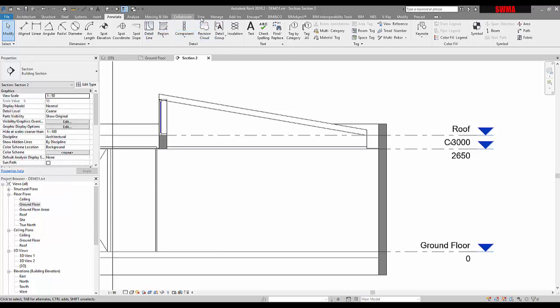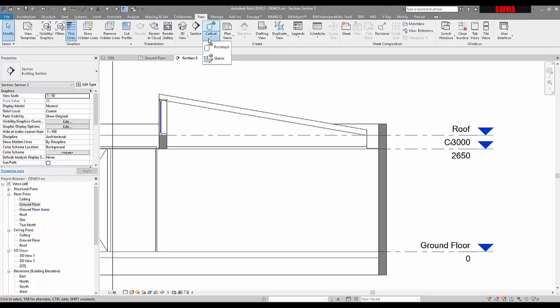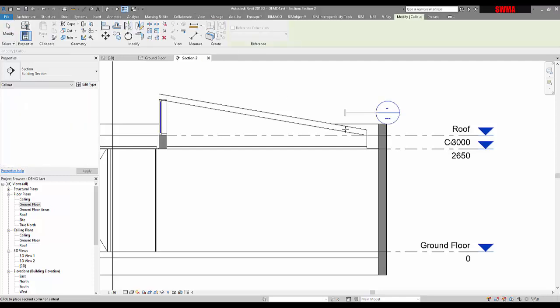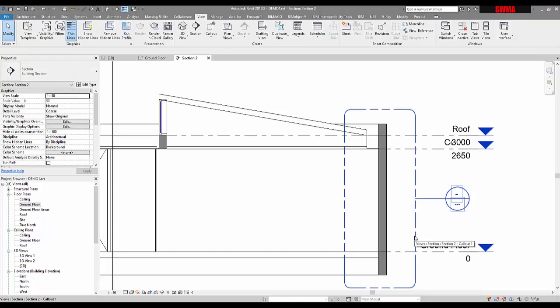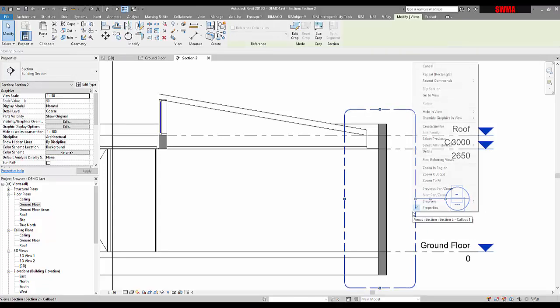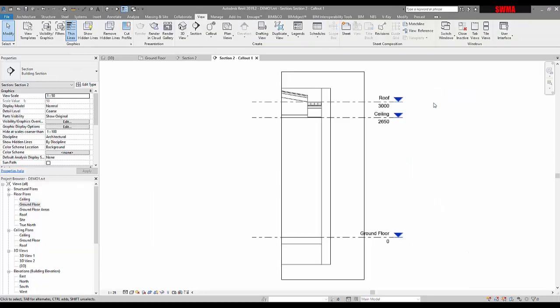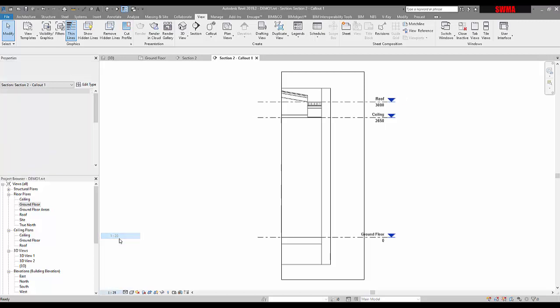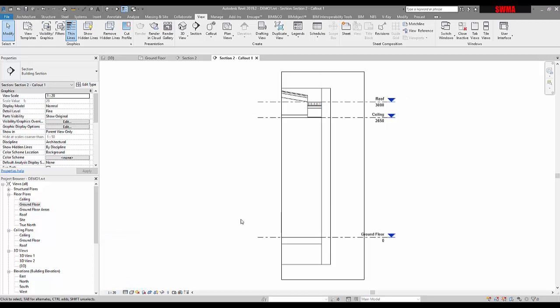So there's a feature here called a callout, and I want to get right into maybe some information on that wall. Instead of having to do everything inside of Revit in terms of the Revit geometry, I can just work up in 2D in the annotation. So I'll go to that view. Now this one has changed scales. I'm going to do my wall as 1:20 and go to fine.